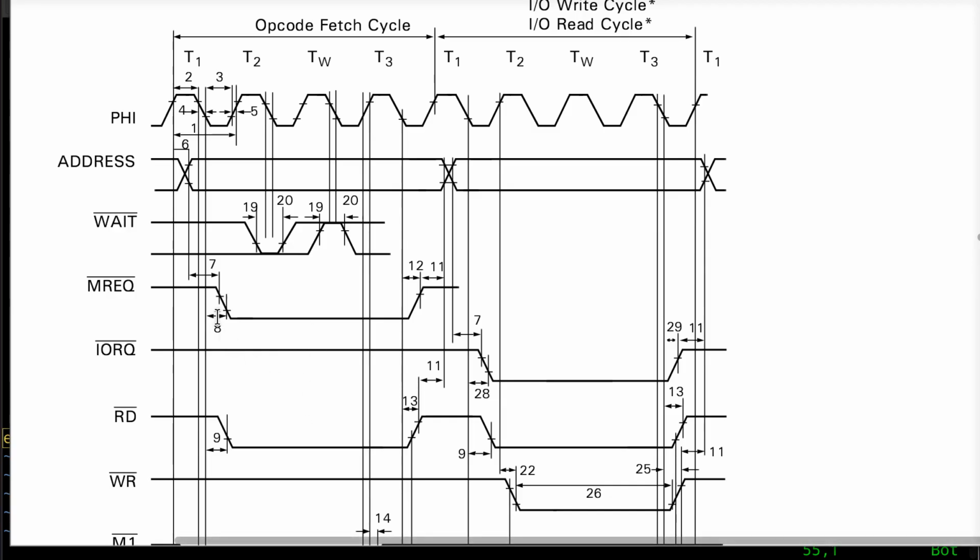So we need to make dang sure that we end up seeing this falling edge without our signals being true. And in a memory transfer, it would be MREC and read that would be the earliest things that are going to happen after the falling edge of T1, because a write, like here, would go true way over here, after the rising edge of T2.